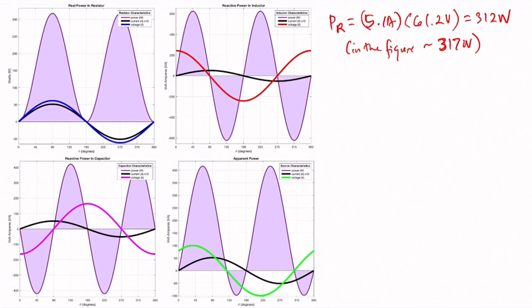In the upper right figure, you see the power in the inductor. The current again is scaled by 10 and the voltage is scaled by 1. And the power you obtain by multiplying the current and the voltage waveforms. The current is out of phase with the voltage by 90 degrees, with the voltage across the inductor leading the current. And you can see this alternating power from positive to negative to positive to negative, meaning that it's consuming power, and then it's returning power, and then it's consuming it again, and returning power. And that's for an ideal inductor.